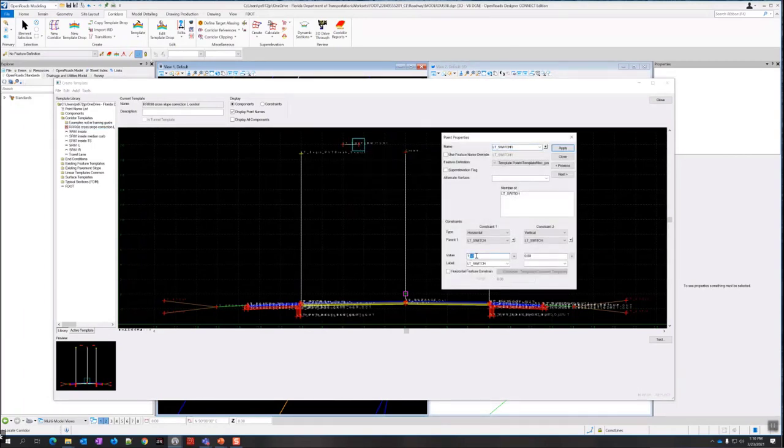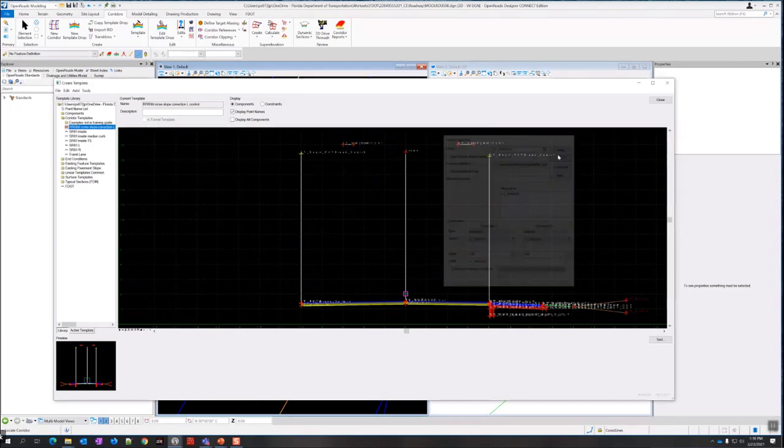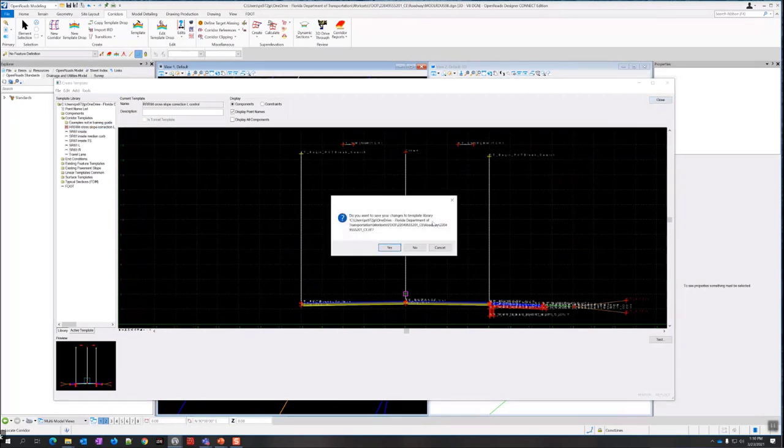So when this value changes to 1, change that to 1, and click Apply, you can see that whole side goes away. So that's what's happening here: we're overriding this with this label here on the parametric constraint, this horizontal distance, and this has a display rule that ties it to this. So that's all that's doing. I'm just going to close this without saving it.